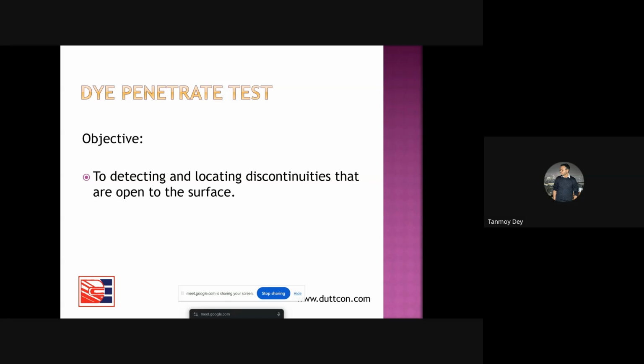So we remove the slag through hammering, and we don't know whether the welding is proper or not. Welding may have so many defects. It may have porosities, slag intrusions, less penetration, not penetration to the root. Till the root, it is not introduced. So we have to understand whether the welding is good or not.